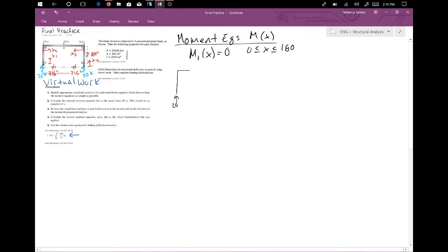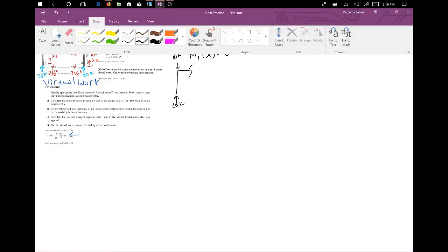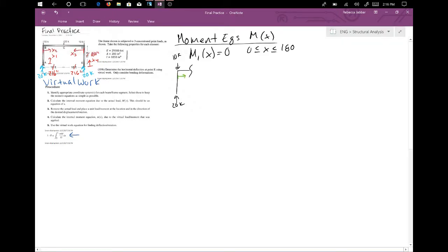We got 20 kips here, we got 10 kips here, and then this would be where our section cut, and we'll have our x2 extending from there. So this whole horizontal distance is considered x2. We don't just say that we're cutting 2/3 down BC and then calculating that. That whole length is x2. And then we're trying to get this moment right here.